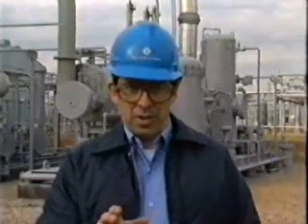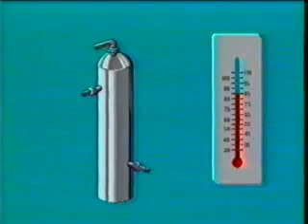In cold weather, line heaters heat the gas stream ahead of the dehydration unit to maintain a minimum inlet gas temperature of 50 degrees Fahrenheit. Minimum inlet gas temperature is set by the viscosity of the glycol being used. Depending on the composition and pressure of the gas, hydrates may form at temperatures well above 50 degrees Fahrenheit. Therefore, a higher inlet gas temperature is required to avoid plugging problems from hydrates.